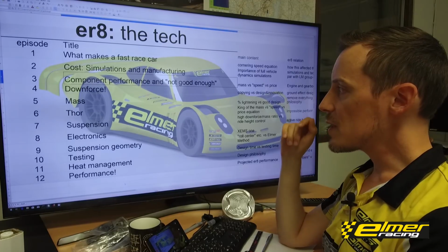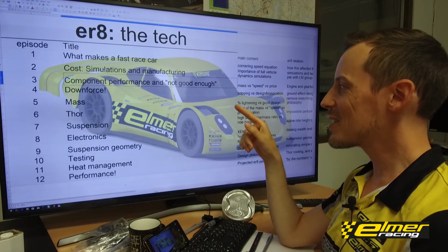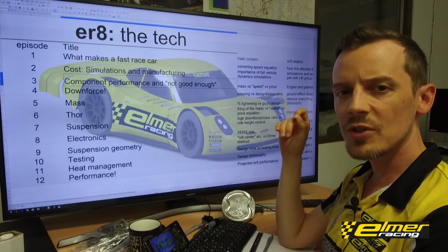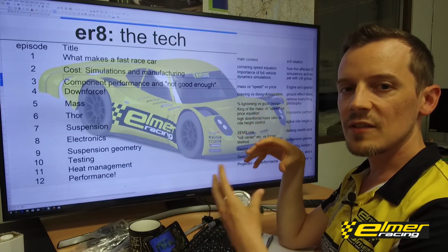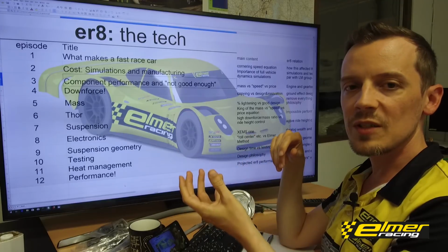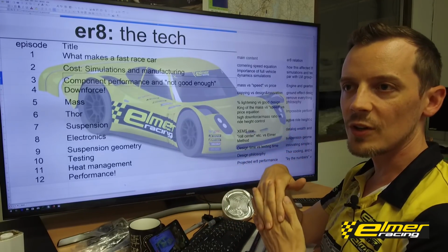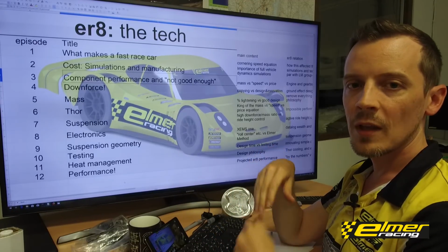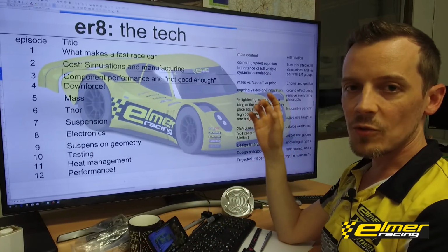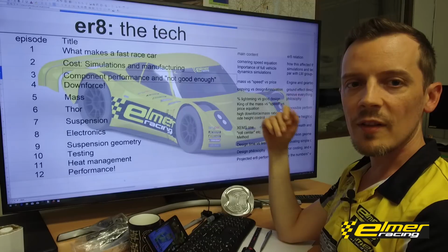But yeah, for this engine, or for the gearbox, we started going through different options. First of all, what size the gearbox would be, so where it would need to be mounted, and if we would want to run a transaxle or not. So that's a gearbox with a built-in differential. And with a transaxle, of course, it's very easy to figure out that would be ideal.